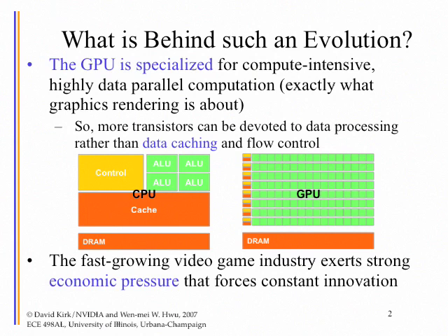parallelism. So when people design a typical CPU, the CPU would look like a piece of control logic with some ALUs, typically about 12 to 16 function units for a CPU. And then there will be a fairly large cache. And this cache memory can be organized into hierarchical arrangements. The first level cache is typically about 16K bytes, and second level is about 256K.